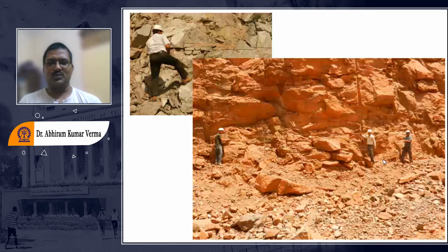You see, these two people are stretching a tape with a length of about maybe 10 to 15 meters. They have gone up to the maximum length of the tape, and we are trying to find out the frequency, the number of joint sets in this particular length. How many joint sets are there?